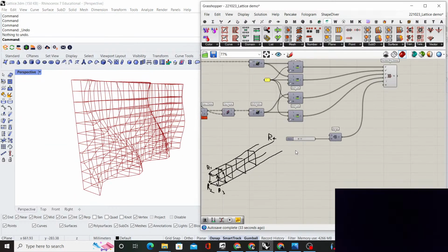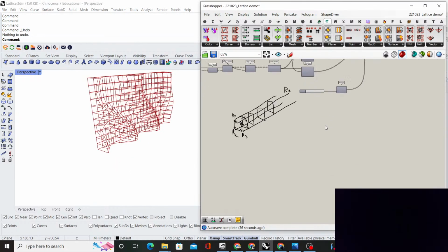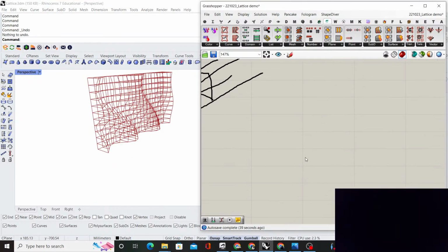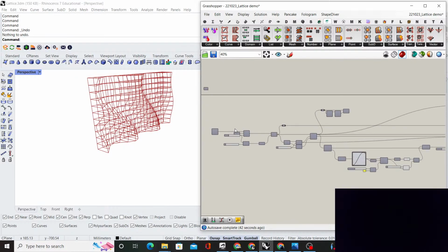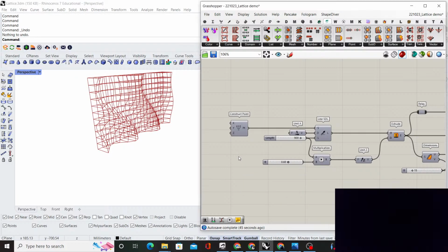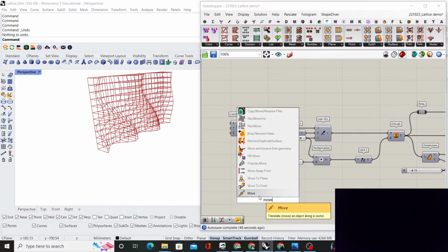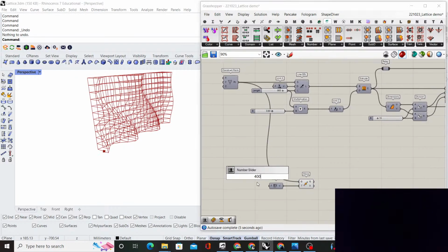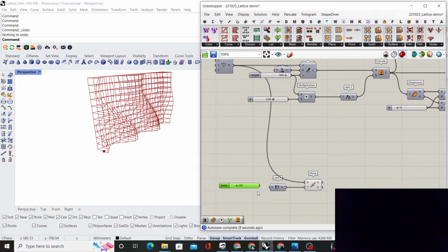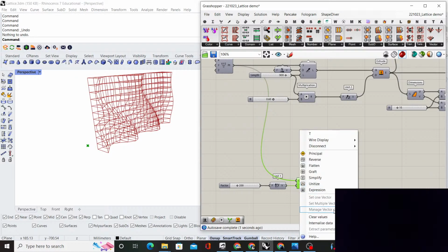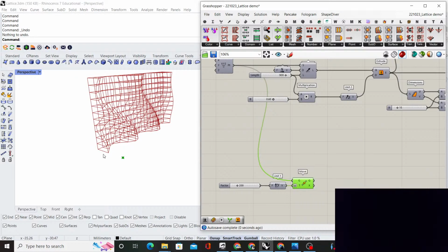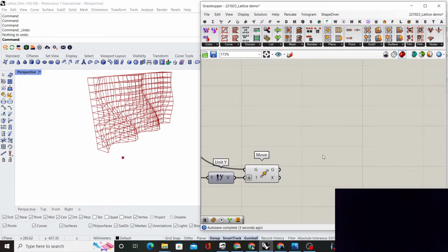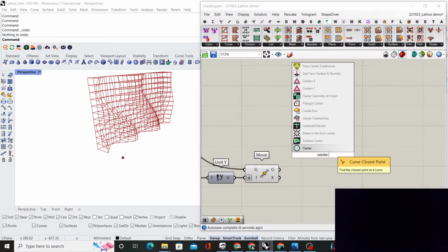We're gonna start making these modules on the ground. So I'm gonna make a really simple exercise. I'm gonna take the starting point and move it a bit forward, so we will have it in front of us. This point, let's move it along the y-axis by, let's say, 400, maybe 200. Should be fine. With a minus x expression. Sounds good. Let's take a center box component.